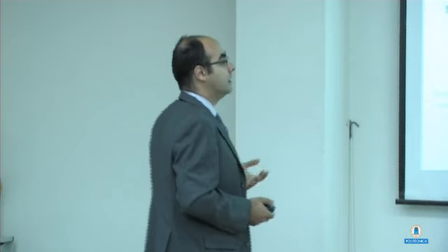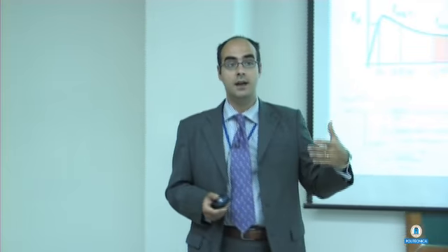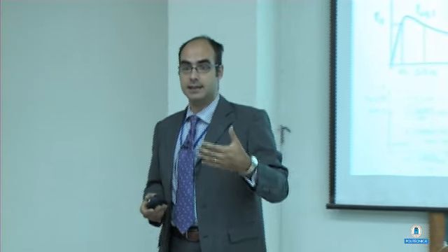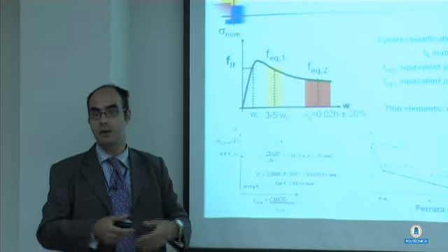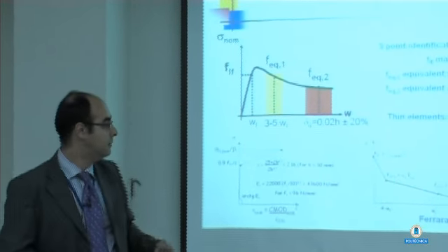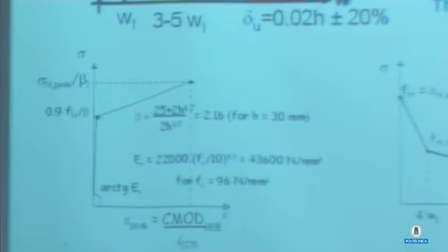We are currently working now on the identification of the relevant mechanical properties for the design. We had good results for the material, for the design of the casting process. Now we want to propose a design methodology with this kind of material. Due to the behavior that we had, a pre-peak multi-cracking stage and a post-peak unstable crack propagation, we proposed a pre-peak stress-strain law, because in that case we have a continuous material, and a post-peak stress-crack opening law, as is common for this kind of materials.